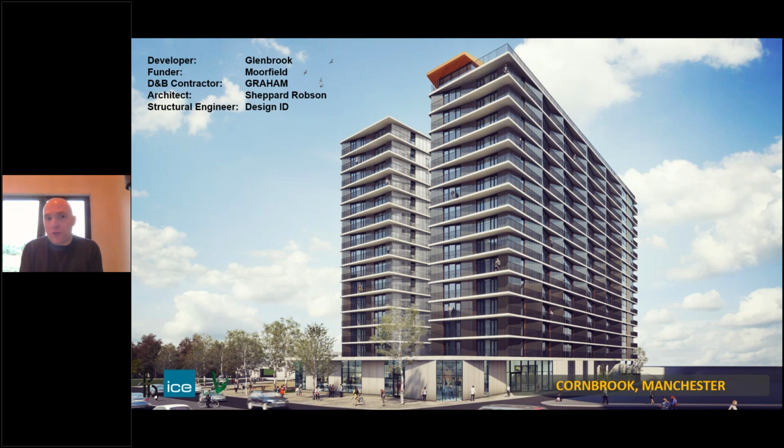So we worked very closely with Graham and said, when are you going to put the envelope onto the building? At what point in the construction program are you thinking of putting the external facade in? When will the concrete frame be constructed? When will it be struck? How much of the dead load will actually be there? How much of the creep of concrete will have actually occurred?